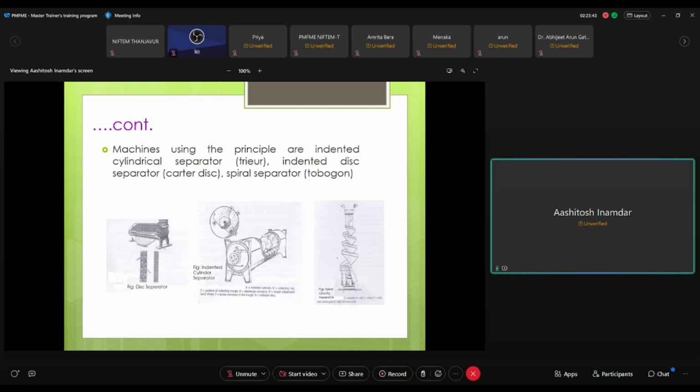Of course, whenever we separate certain impurities, it's not that 100% separation will happen, or that 100% of impurities we are going to throw away. Let's take the example of wheat. Suppose this machine is placed in a wheat processing unit. We will get broken wheat, maybe smaller wheat, and impurities like mustard all coming together from the top. These we don't want to just throw away, because we may want to use the broken wheat or the shriveled wheat back in the system, based upon the batch you are going to process.